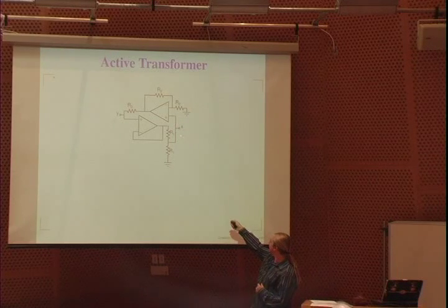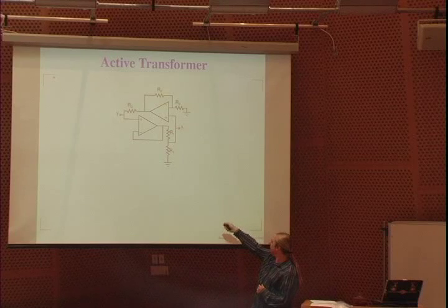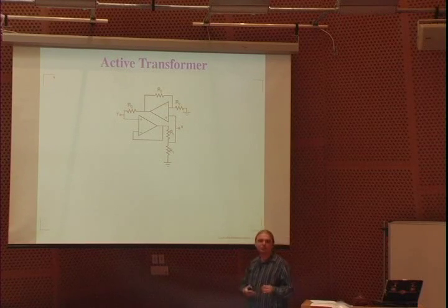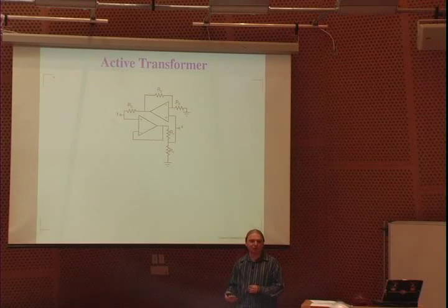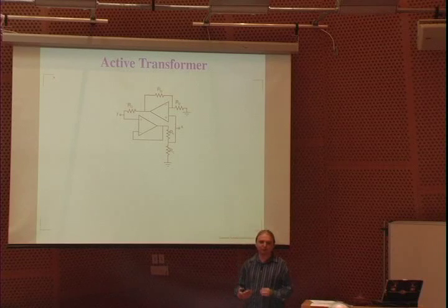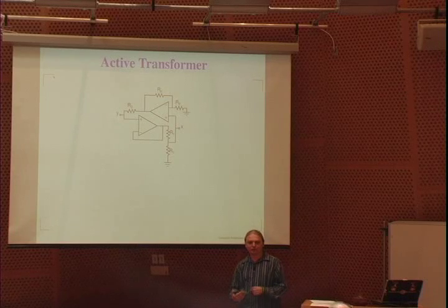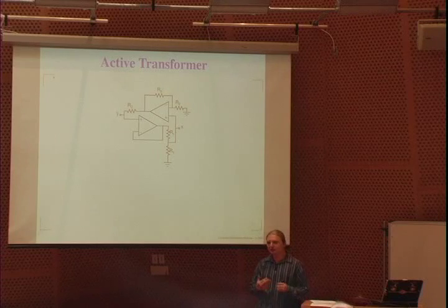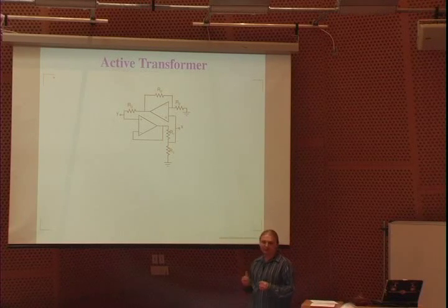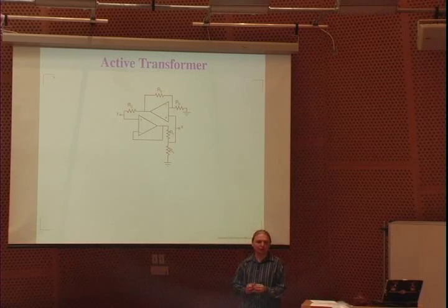For the circuits guys, I have a gain of 2 from x to y. I have a gain of 1/2 from y to x. And if it's exactly what it should be, it will be a passive component and it will behave similarly to a transformer. If, on the other hand, I make an epsilon error, it will no longer be passive, so I need a different stability criterion. In addition to that, I can't use the exact transformer model because an ideal transformer guarantees that